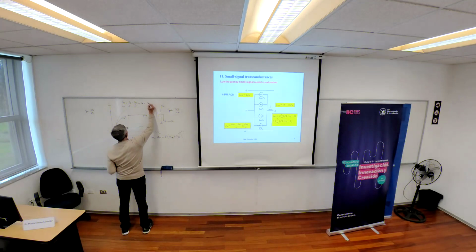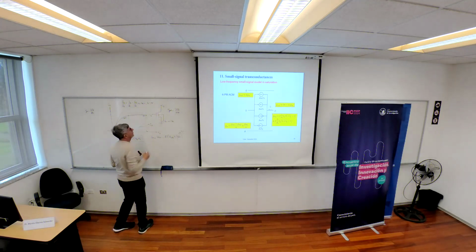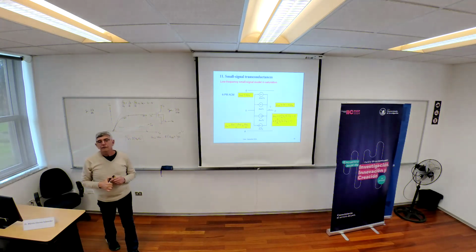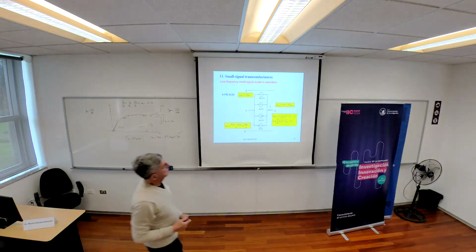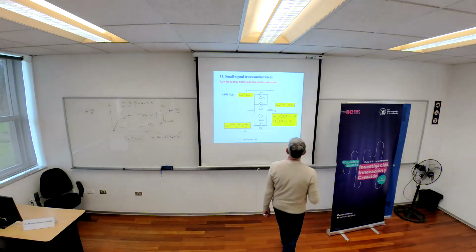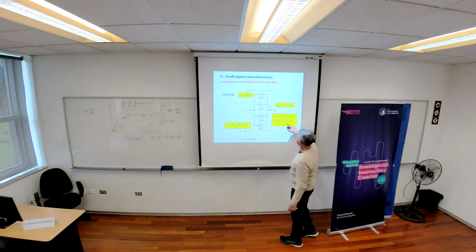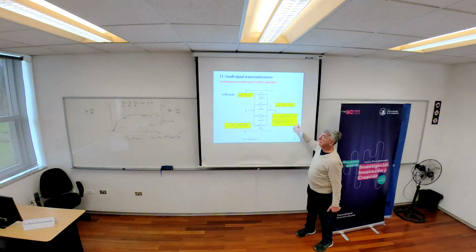Small IF is the normalized forward current, and small IR the normalized reverse current. Now you can write GMS in terms of the inversion level. In saturation, IF is much greater than IR.